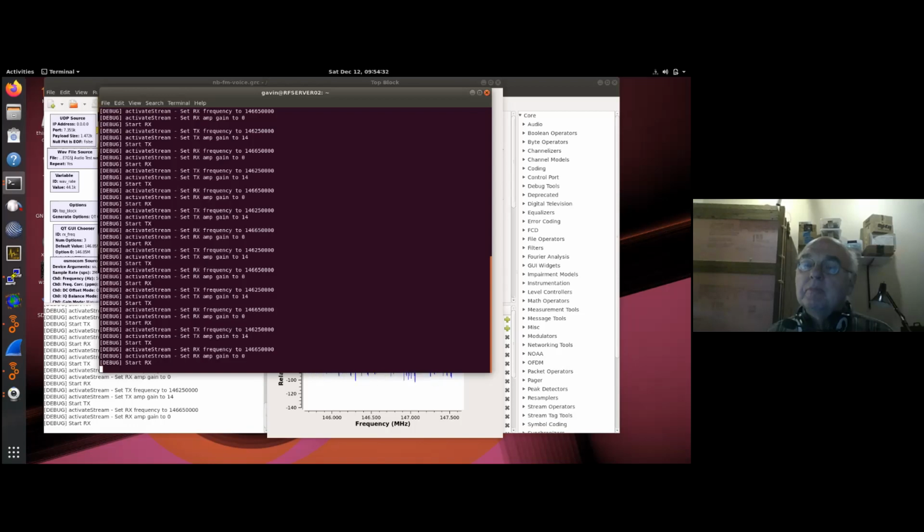I have a line device connected, and when I want to talk, I just press a button, and then the relays switch on for a selected path. Say I have the amplifiers and the RF switch on a transmit path, and when I stop transmitting, the relays will switch off, and therefore the RF switch will also toggle back to the RX path.